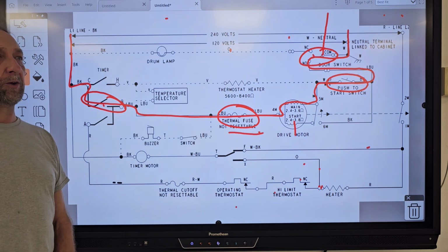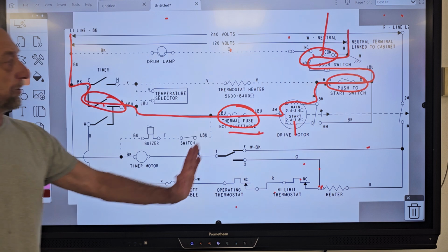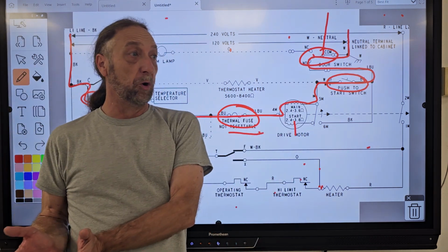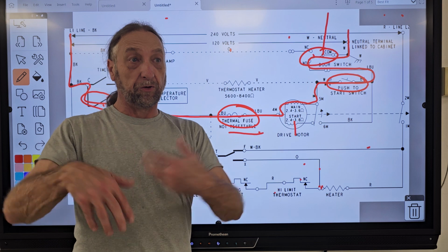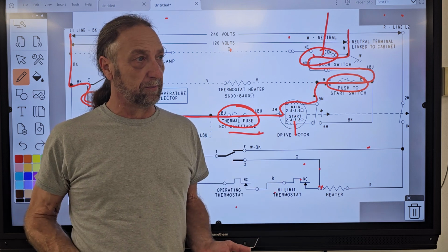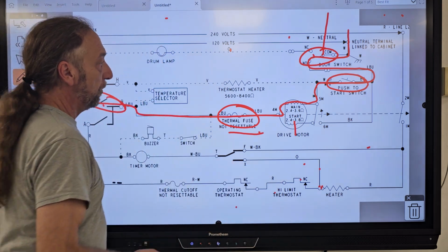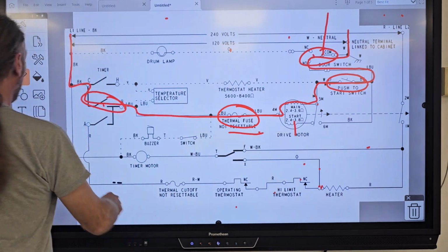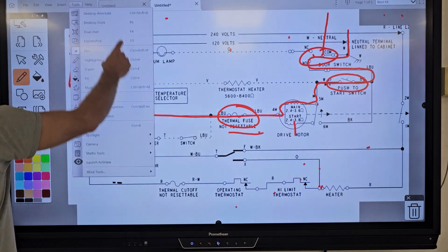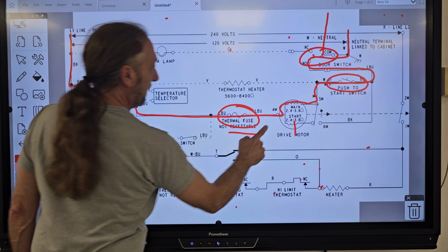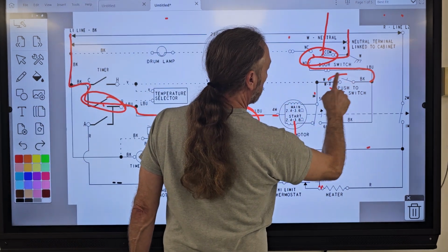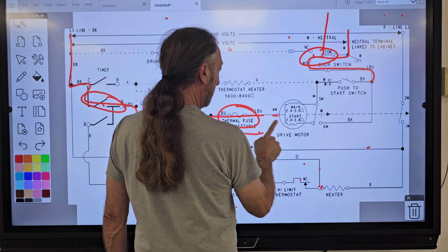We don't put a voltmeter across a switch. We put a voltmeter across a load. A meter is just like a motor. The needle moves, it's just like the motor that runs. So we want to go to the motor, but the motor's too hard to get to. So what we do is that, how close can I get to the motor without actually being at the motor?